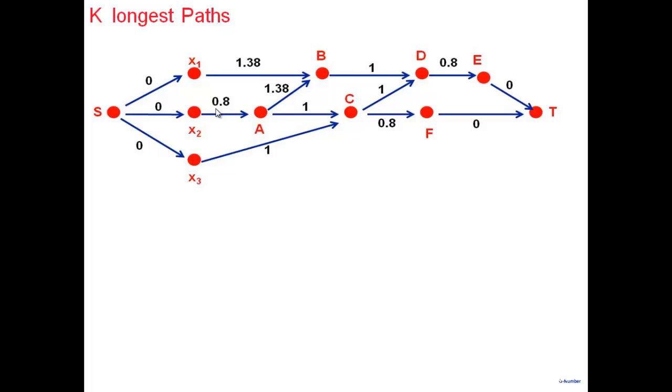A data path and a controller. After I do a data path and a controller, then I have these blocks, registers and adders and all of those things that are there, and a control unit. I convert all of them into a gate level, and in the process we looked at logic synthesis. How do you minimize, and you do technology mapping and all that, and you have a gate level description here.